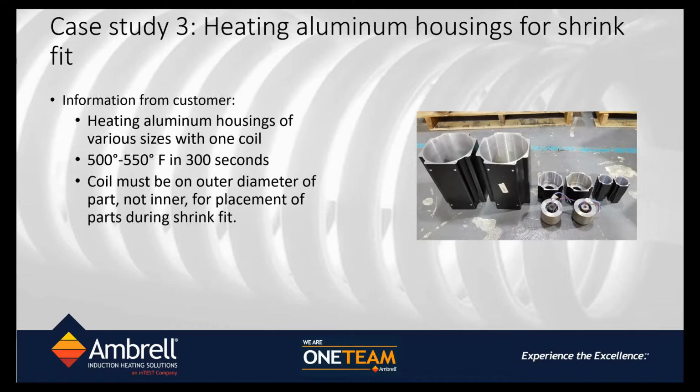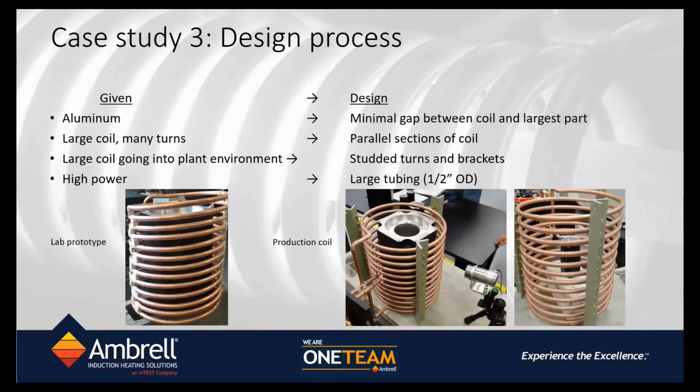Aluminum is such a good conductor of heat that even though we designed one large induction heating coil to heat the largest of the parts, it was still able to heat the smallest of the parts, because the induction heating power supply was automatically able to tune and resonate and deliver energy to the small part as well, not at utmost efficiency, but still able to do the entire operation for the customer with one standard coil design.